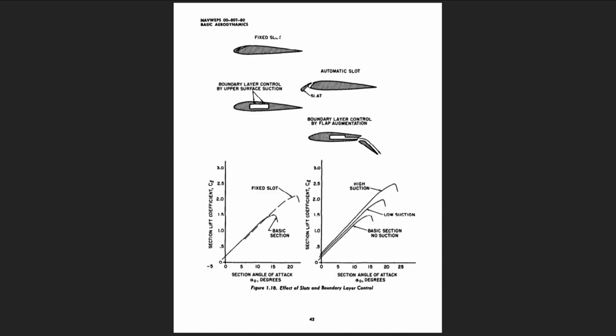High lift devices applied to the leading edge of a section consist of slots, slats, and small amounts of local camber. The fixed slot in a wing conducts flow of high-energy air into the boundary layer on the upper surface and delays airflow separation to some higher angle of attack and lift coefficient. Since the slot alone affects no change in camber, the higher maximum lift coefficient will be obtained at a higher angle of attack, i.e., the slot simply delays stall to a higher angle of attack.